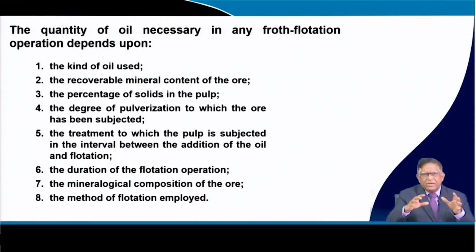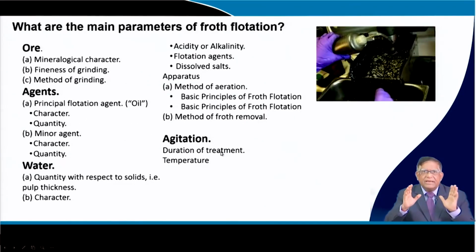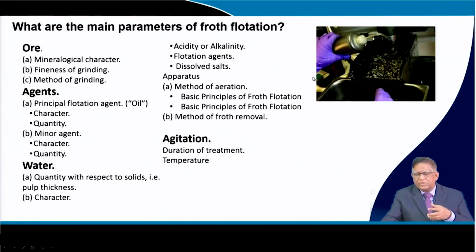And the mineralogical composition of the ore, then the method of flotation employed, that is whether you are taking it in an inclined way, or you are taking it out just horizontally, all those things are taken care of. That means while you are going to design these things in real life situations, these factors will have to be taken into consideration.